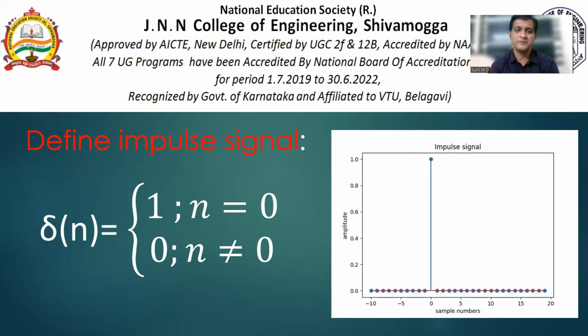Okay, in continuous time it is infinite, we say, or something that cannot be determined. Fine. At n equal to 0 it is 1, and it is 0 for n not equal to 0. But in discrete time, it is 1. So what is it here? This is how the impulse looks like. It is a sample of 1 at n equal to 0, right?